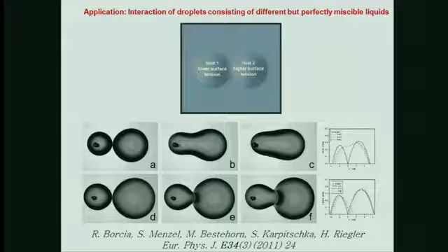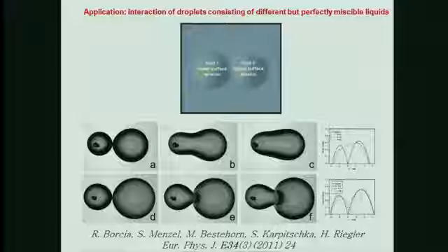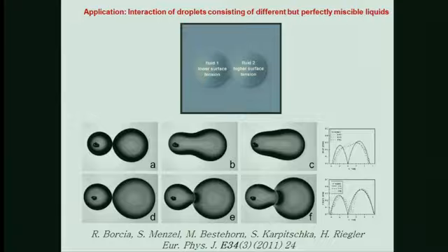So what we have now, we have 2 liquid drops in a gas atmosphere. The contact angle is low, between 10 and 20 degrees or maybe more. And they showed here that the 2 drops have the same density, the same viscosity, the same contact angles, but different surface tensions. And when put in contact with each other, it is expected to appear a coalescence assisted by Marangoni forces, acting from lower to higher surface tension.